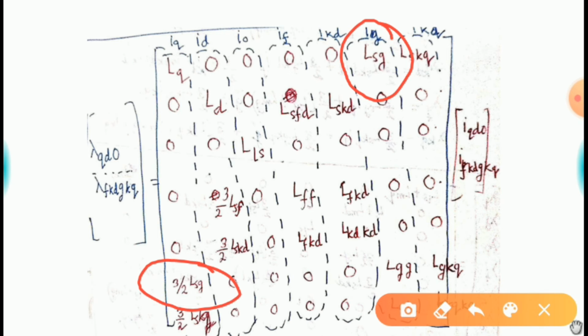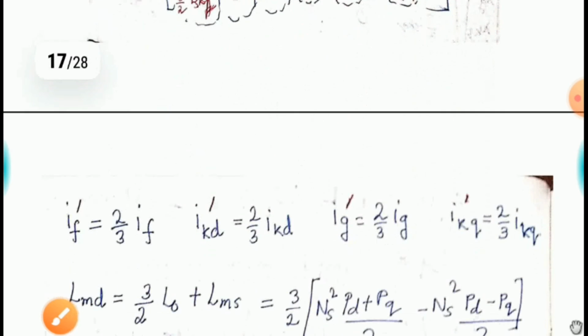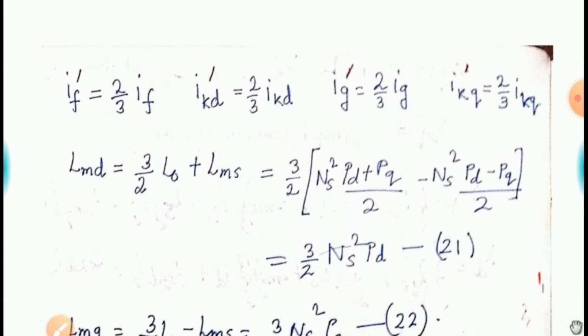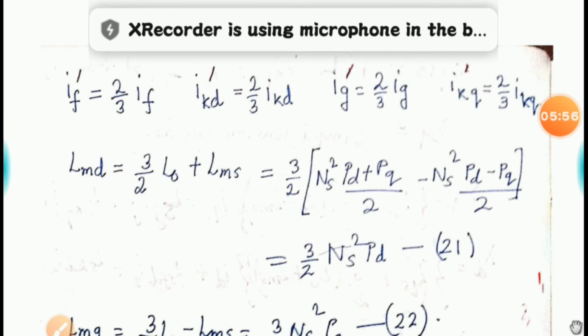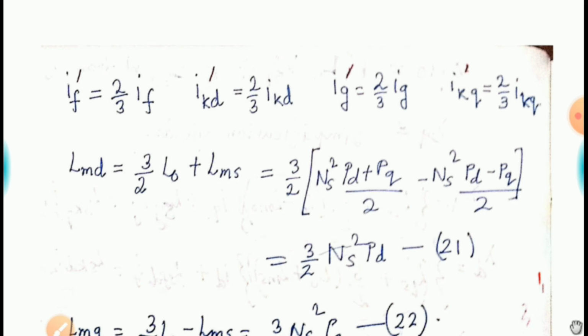But it is desirable that when you have this lambda q, lambda d, lambda 0, it is not only the removal of theta dependency in your inductance model, but you should think how you can make it a symmetrical one, because a symmetrical matrix is more handy and reduces our computational effort during computation, right? So in order to make it symmetrical, we have to deal with the annoying terms that make it asymmetrical, this 3 by 2 factor.